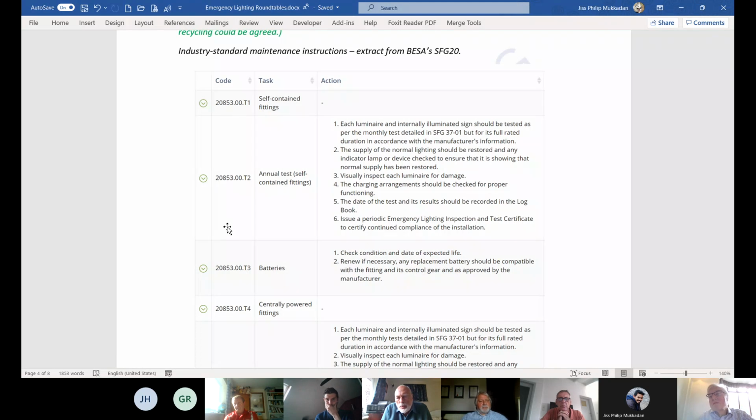No, not the exit signs, Chris. Forgetting the exit signs, bear in mind that in 5266, even a first aid box has got to be illuminated. That's correct. So unless one follows the other, the likelihood is that you're moving the first aid box to a luminaire. If that's okay, that's okay. But if one is a separate contractor to the other, then you've got a problem.